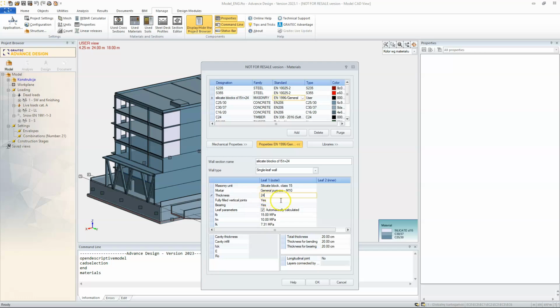I can also specify a thickness. It's a new approach in comparison to other materials because we usually had a material and the thickness was related to a certain element. If it comes to masonry material, it's done differently, however, because it's related to a specific block. And also, as you can see, you can use many different wall types. So it can be single leaf, it can be double leaf, it can be cavity, and so on. And the mechanical properties are steered with the thickness.